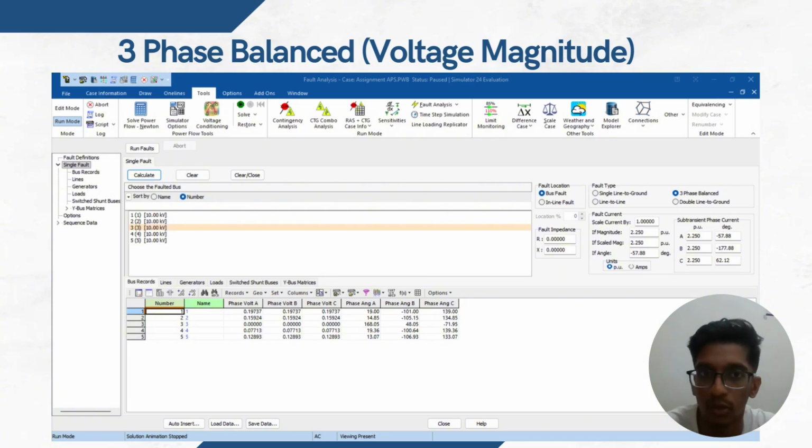So a three-phase voltage fault at bus 3 represents the most severe but symmetrical disturbance. This graph shows that voltages at the fault location drop to zero on all three phases. Voltages at remote buses will also sag significantly depending on the system impedance. This simulation is the primary input for transition stability studies and determines the maximum short circuit current for breaker duty calculations.